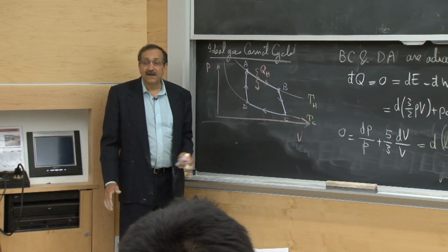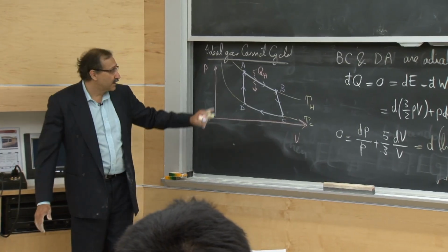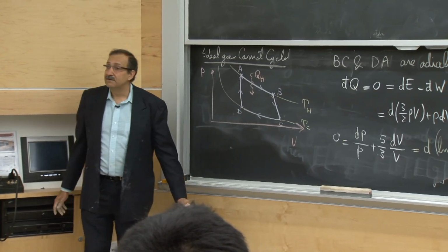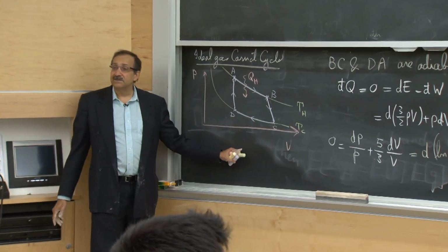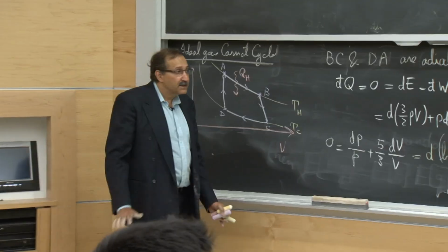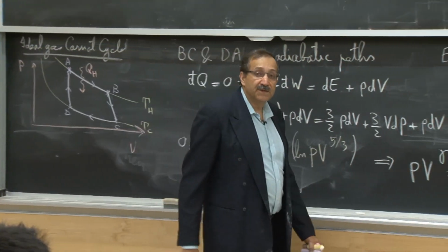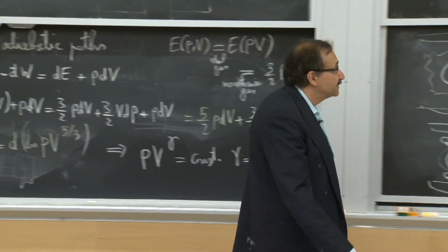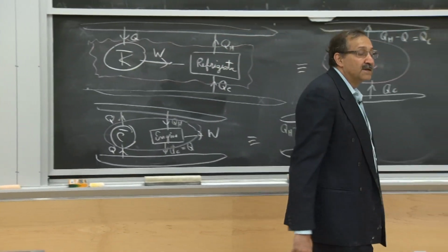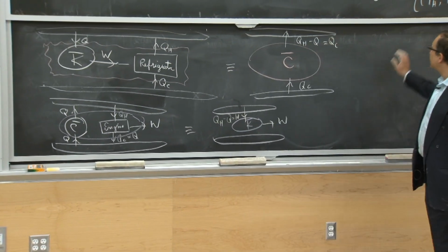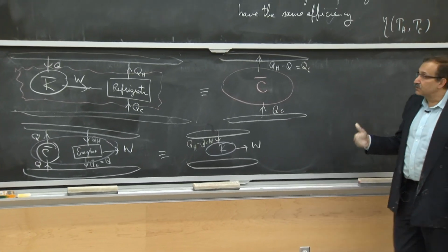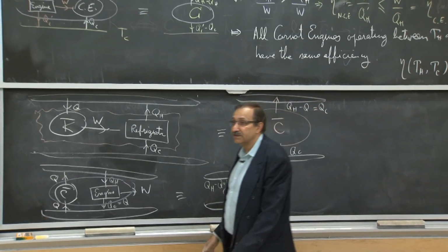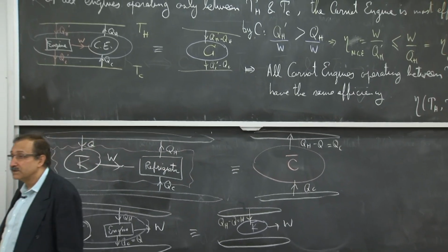As long as with that substance I can construct some kind of a Carnot cycle, irrespective of what the coordinate systems are, what the isotherms look like, etc. Just working between two temperatures and two isotherms tells me that this reversible cycle will have this efficiency relating the amount of work and the amount of heat that is exchanged as you go around it. Okay?